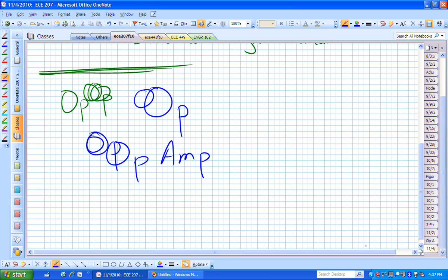We know those are true. And we just found earlier that R2 I2 was equal to R sub 3 I sub 3. That was why maybe we chose I3 in the direction that we did. There's no negative sign in this relationship. So I sub 2 is just a constant away from I sub 3. I can now solve this for I sub 3 and say that I sub 3 is R sub 2 over R sub 3 I sub 2.